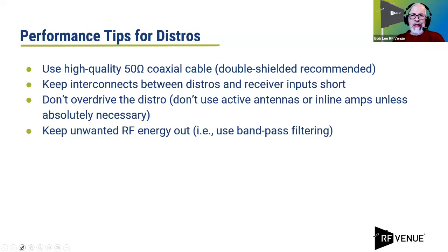Mobile phones are ubiquitous. Everybody's got them. If you're working with an audience, you can figure you've got hundreds or thousands of mobile phones in the audience, and people aren't turning them off for a show. So you have to learn to contend with that. And so we recommend using bandpass filtering on any wireless mic receiving system. Nobody ever regrets bandpass filtering their wireless mic system.